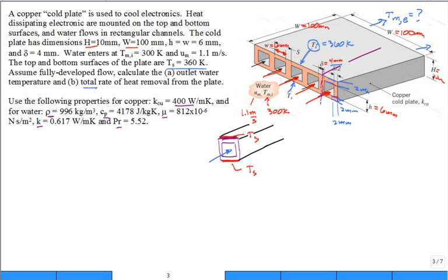Well, how does the heat transfer into that water? Well, you would say that it transfers directly across this copper section, but it can also travel up in that webbing and then into the fluid. So it can come up on the sides and into the fluid. What we see is the bottom acts like a plate that offers some conduction resistance, but the top parts, the sides, act as fins.